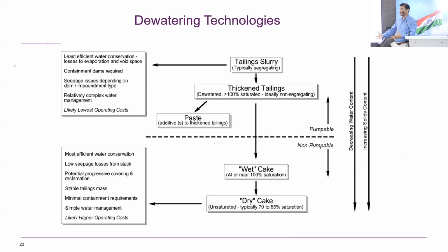Earthquake, that also happens. Yes, but in that case, the earthquake magnitude may be very big or a high value, because these are very fine materials. I did some analysis for earthquake liquefaction, or the dynamic liquefaction, and I found that these materials are not prone to liquefaction under, say, 0.16 g or 0.24 g. For dynamic liquefaction, you may go up to 0.36 g, then these are liquefiable.